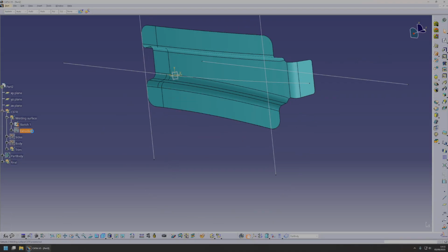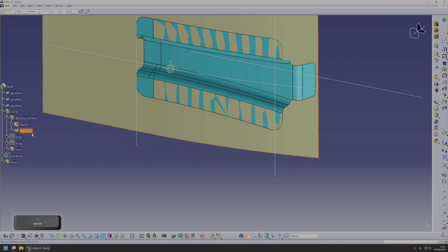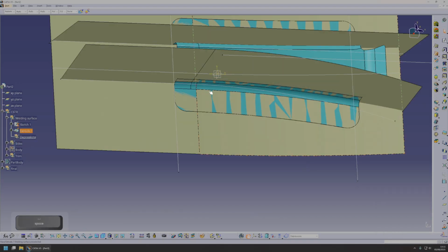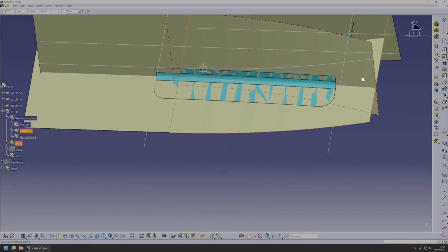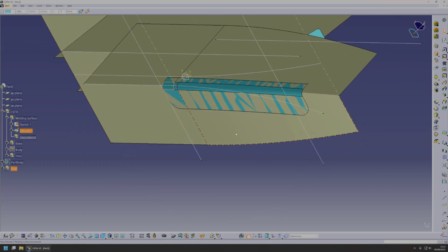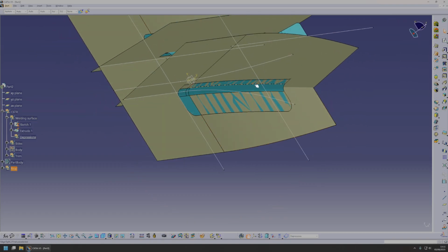To change the welding surface, our welding surface is basically this one. What we need to do is we're going to replace this with a new surface that we're going to create inside this set. So in this welding surface, we're going to create a geoset called depressions. First things first, we need to have this intersection to generate this curve, because what we want to do is basically pattern them around the curve that is going to be this intersection between this surface and this one.